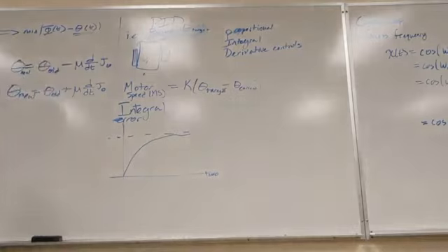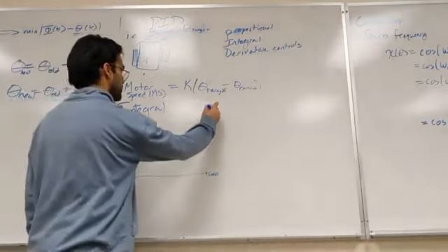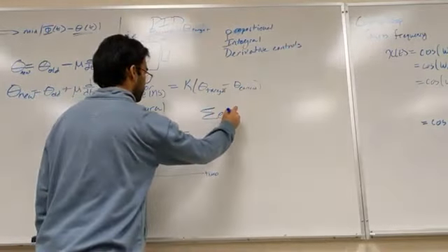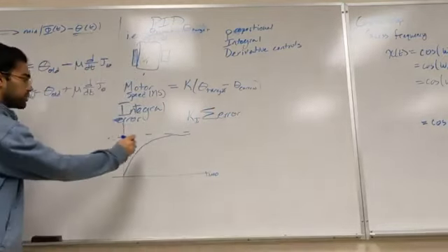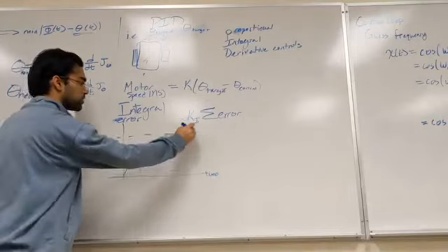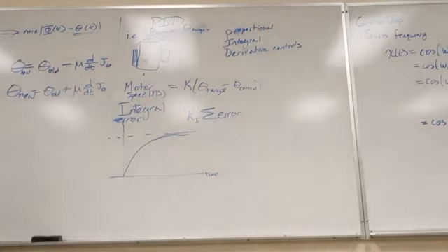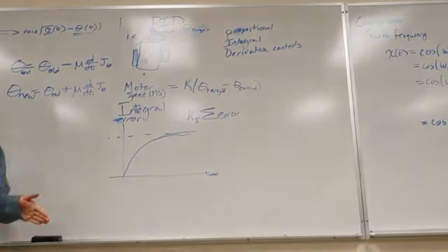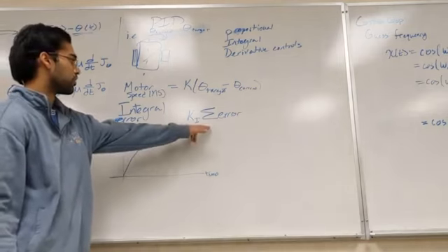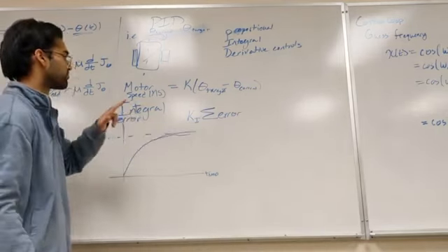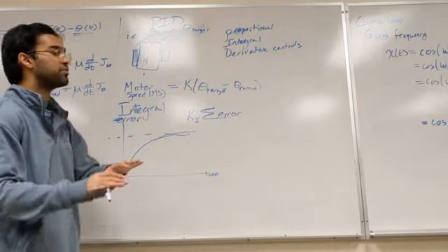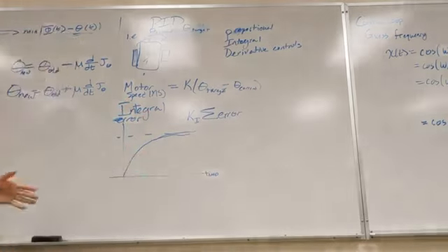With an integral controller, which is you just take the sum of your error over time, times some constant, you will eventually converge onto this. Because you're taking the average error you're away from it, and you're using that to align to the target. Okay, that's a bad explanation, but